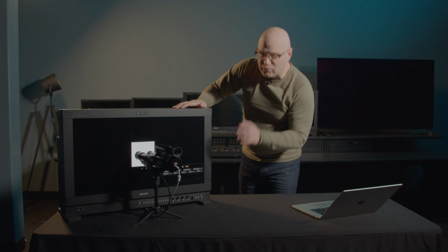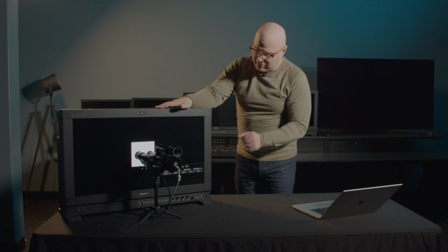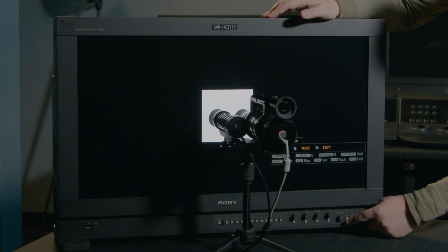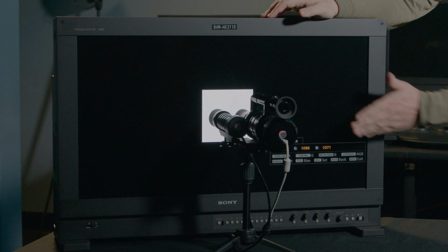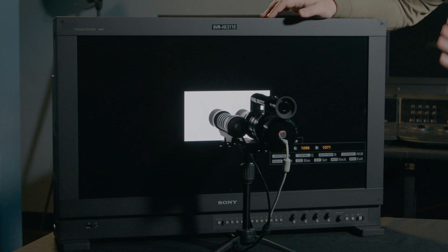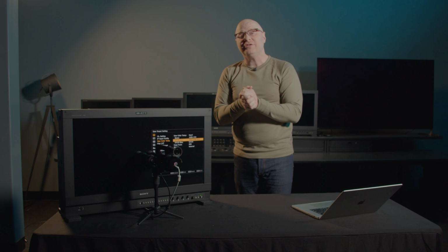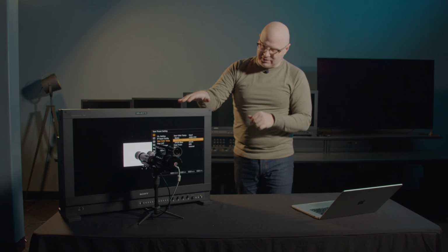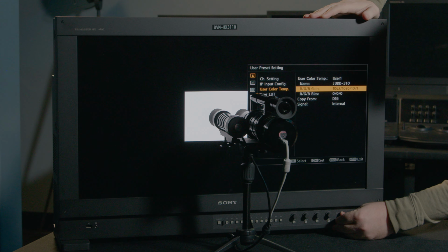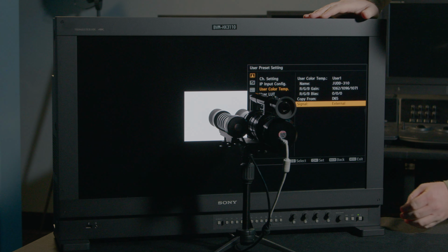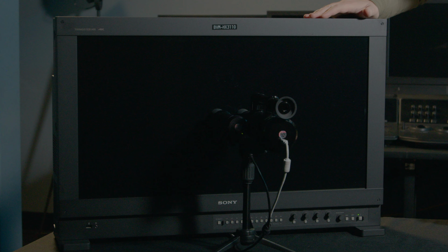All right. There's one more thing you should be very careful of when you're calibrating this display. When you're in the white balance control, if you do press back or menu, you're going to lose the adjustments you just made. You're going to want to hit the select enter button to save those adjustments. Another thing you might have just noticed is that we had the display set to the internal pattern generator. So we were white balancing on that internal patch, but let's come down to the signal and choose the external moving forward. I'm going to press menu to exit.